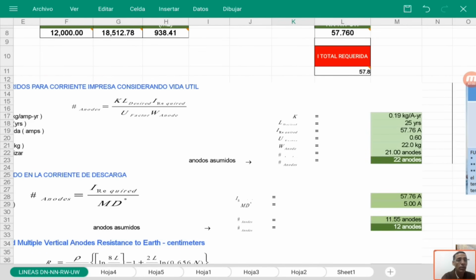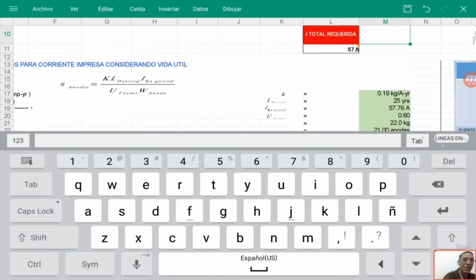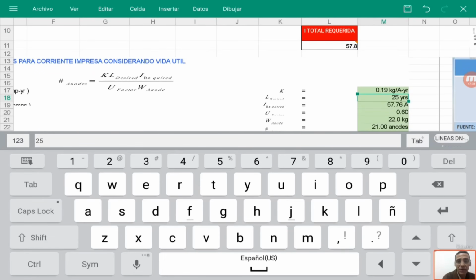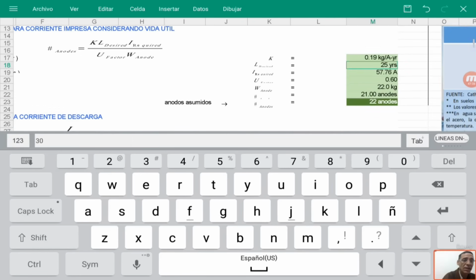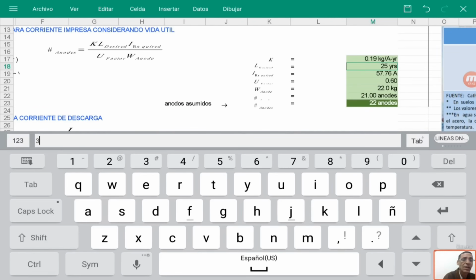This is based on service life, but here it says 25 years. And this utilization factor is usually given to us directly by the manufacturer. But let's say the client specifically told us he wants a full 30 years for this particular table. Let's say the client clearly stated, no, I absolutely want a service life of 30 years. Let's carefully see how much this extended number of years truly affects us, a significant 30 years. It went up from an initial 21 years to a full 30 years, representing a considerable increase.